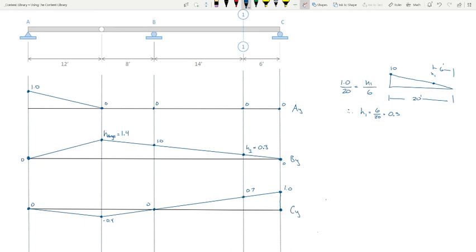So you get some really interesting dilemmas. Like, let's look at the beam. If I want to get the worst case reaction at B and I have a single load, where do I put it? If I'm designing B, like if I'm walking across the beam, where would I be standing to get the worst case effect on B? The hinge, right? Because if I stand right over B, I'm generating 100% of the reaction.